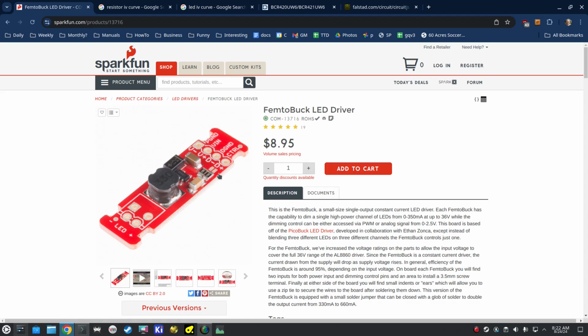But there's a downside. Because it is a switching regulator, that means that it has a square wave that's being generated at fairly high power. And that creates two issues. One is power noise. So power noise means that this thing is not sucking continuous power from the battery, but it's sucking it in rapid pulses.